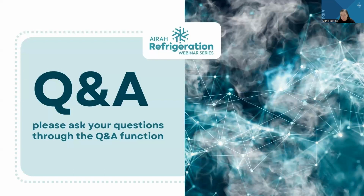Again, as I said, to minimize condensation, obviously the water vapor will eventually find its way to the evaporator. The evaporator is a colder surface, so you condense it on the evaporator. So if it's condensing on the ceiling space, I think there must be something wrong with the integrity of the ceiling insulation, because as I said, the water vapor will go to the coldest. It's all to do with the dew point of the air in the room. That's what causes the condensation. We look at the psychrometrics of the air in the room, the temperature, humidity, and so on.